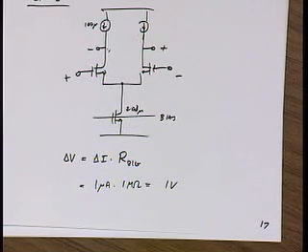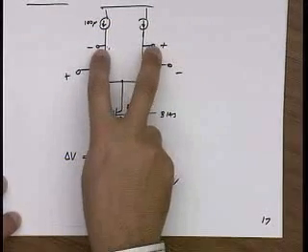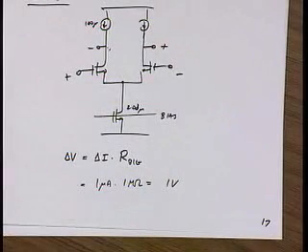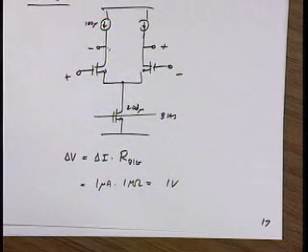Having a common mode range that goes around changes the bias of your transistors. How so? VDS. Let's say I've biased this to be mid-rail, right? Where mid-rail is kind of the high gain point of my amplifier. What's the problem?